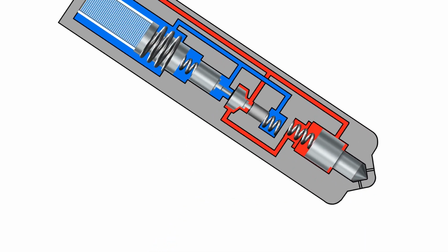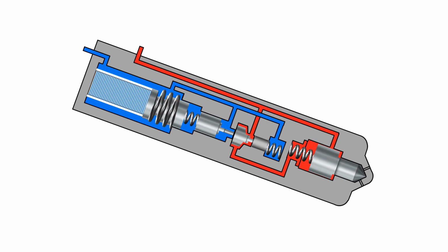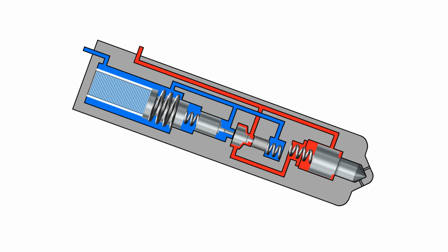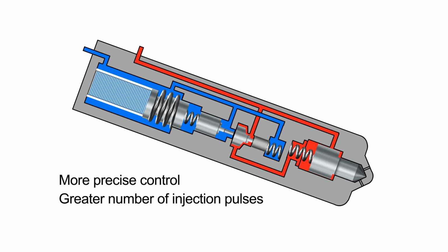the needle. The major advantage of piezoelectric injectors is their speed of operation and the repeatability of their movement. The movement of the piezoelectric stack is almost instantaneous. This reaction speed allows even more precise control and a greater number of injection pulses.